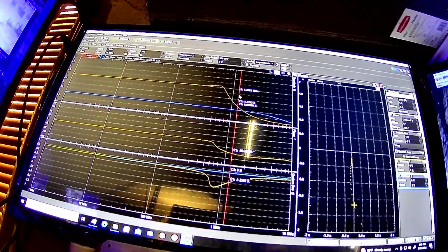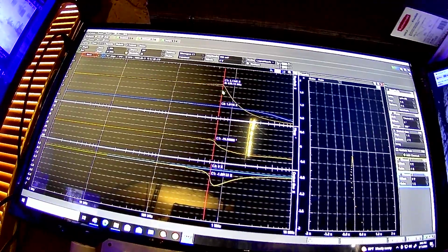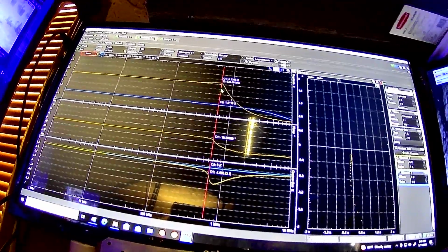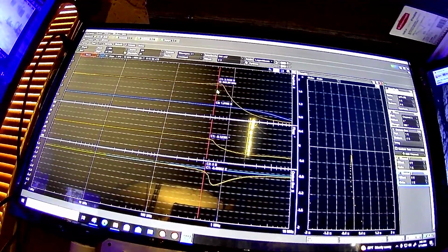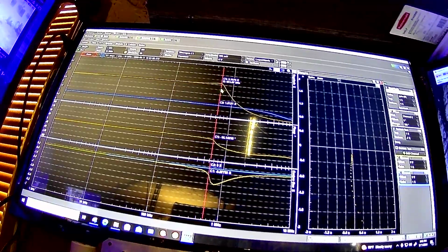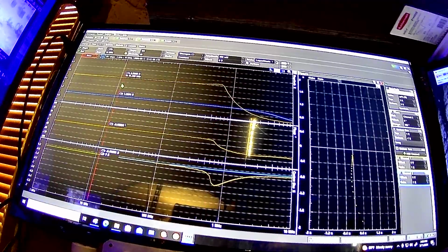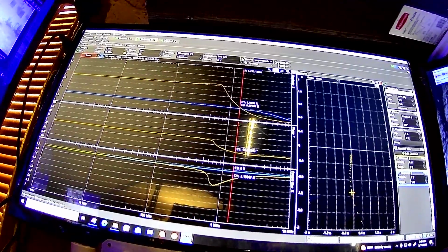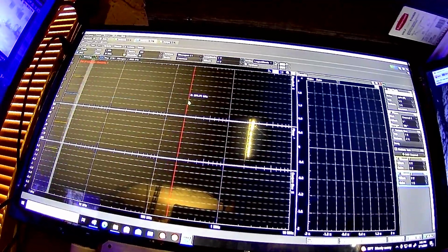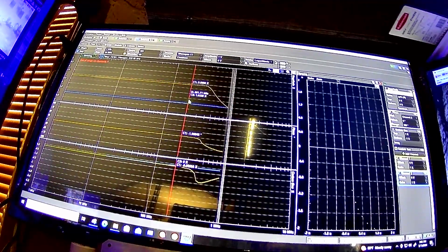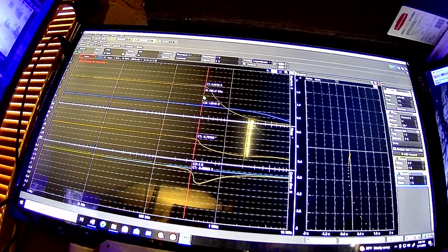So with that being said, like I said, that's 639 kilohertz, because that's our slew rate limit. I guarantee you things would be pretty distorted at this signal level in all likelihood, at that frequency. But at least it's still not bitching at me for having out of range signals. Let's go to 1 volt and see what that looks like. Okay, now it's bitching at me. We're still getting roughly a gain of 3, but the hump has almost completely disappeared.